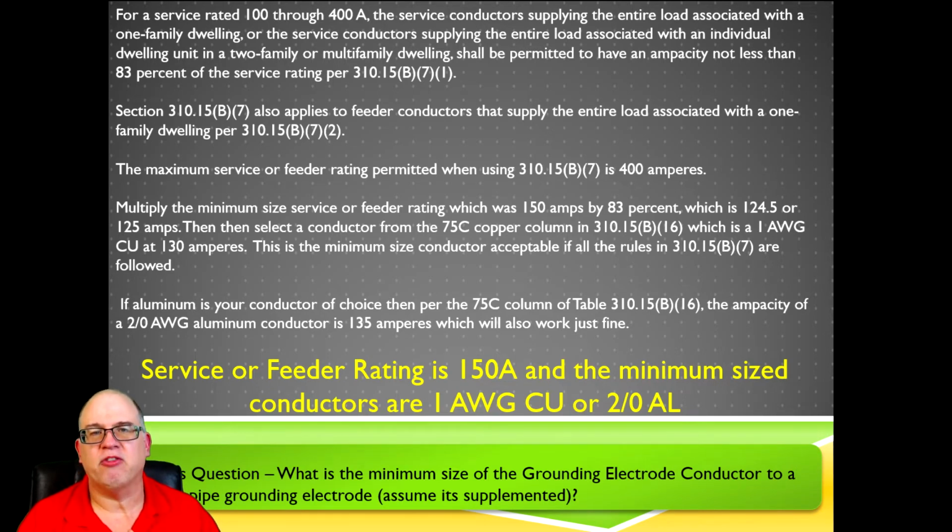But when we have 100 through 400 amperes and it is a single phase 120/240 or single phase 208Y/120 application, then I am going to be able to utilize 310.15(B)(7). And it's a beautiful thing. So again, real quickly, let's go to the code so I can show you that table, because as long as you comply, this thing is going to be a lifesaver for you in sizing.